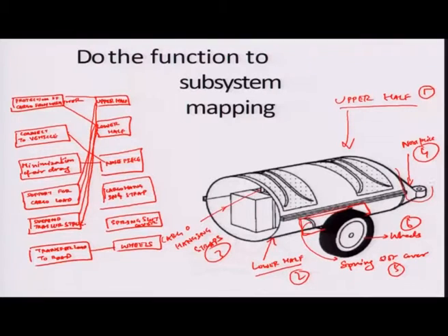The nose piece is this one piece again, which contains both the hitch as well as the fairing combined into one module now. And then of course, the nose piece also in a way supports the cargo load, because if I looked at how this nose piece is biased, it gives structural stability to the upper lower assembly, okay. So, in a way it also is responsible for supporting a part of the cargo load by giving it a stiffer orientation.